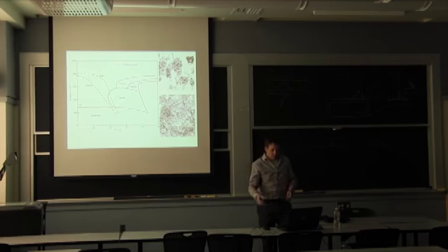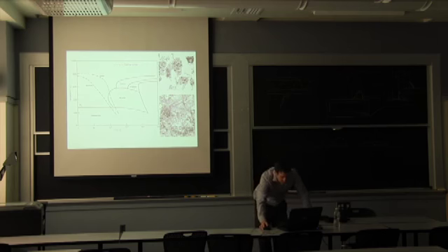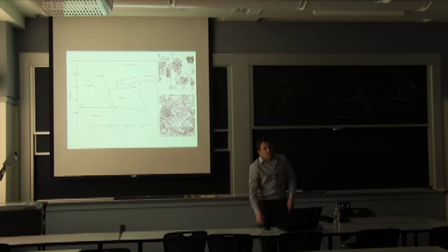So pearlite here forms at high temperature. It'd be the softest. And then you go to bainite, that's essentially a tighter microstructure, and you're increasing the strength. And when you go to martensite, now you're very hard. You have a very high yield strength, but you're also very brittle.